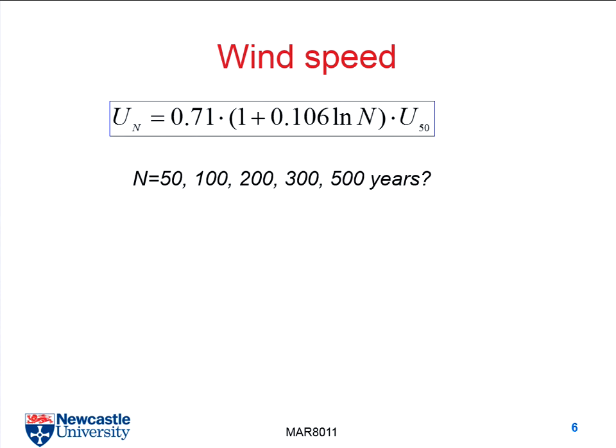So it means if we have a design with a longer return period criterion, we will have a safer design, right? Because you assume that we have a greater wind speed, and you should leave more margin for that. It means your structure is safer, or your design is safer, right?